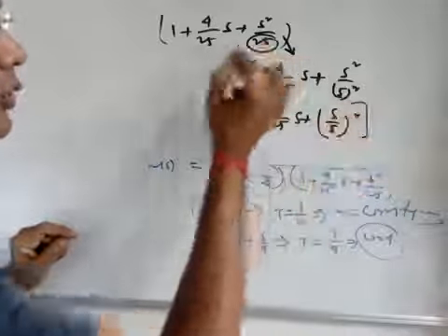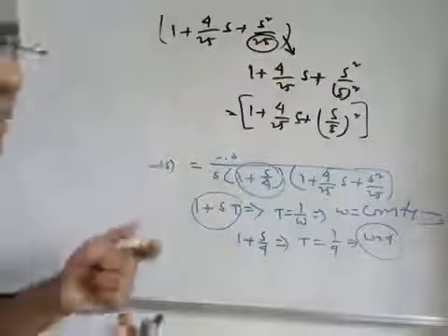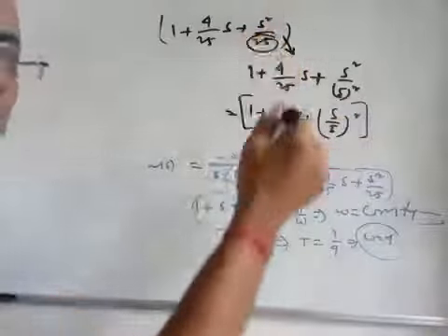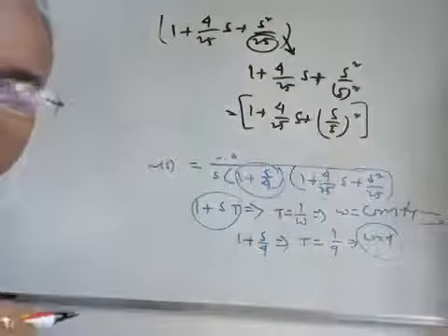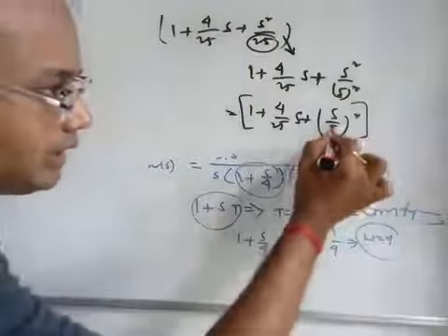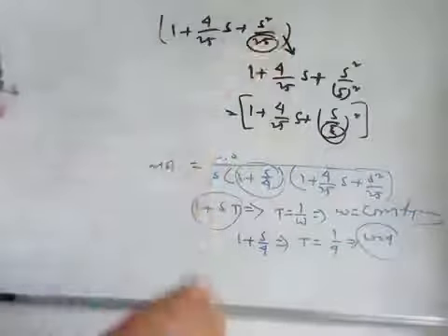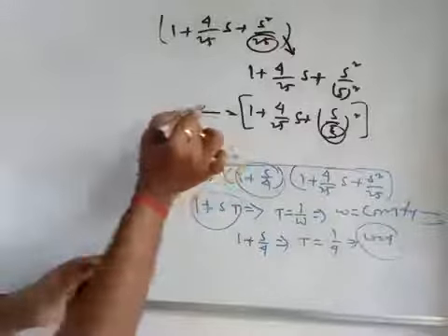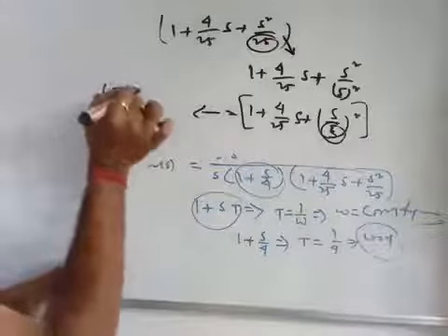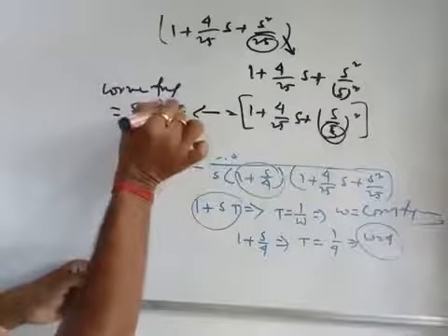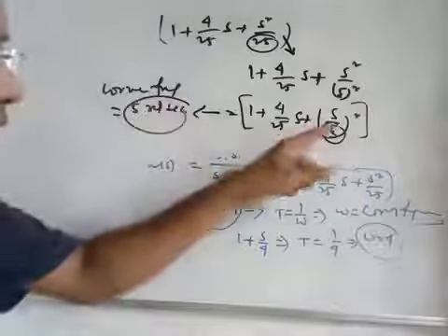So this need not be 25, this may be like 30. That means you can get root over 30 square. This can be 40, so root over 40 square, it can be expressed like this. So this part is the corner frequency corresponding to this second order factor. So the corner frequency for that will be equal to 5 radian per second, right? That is this part.